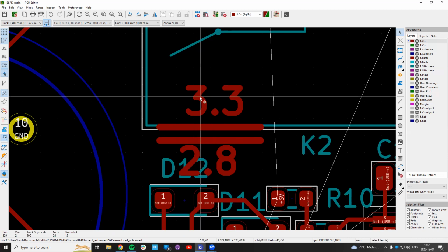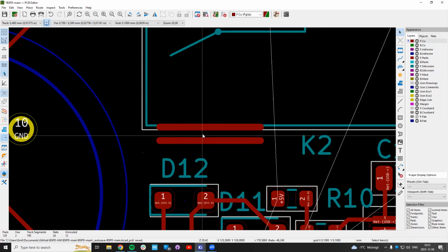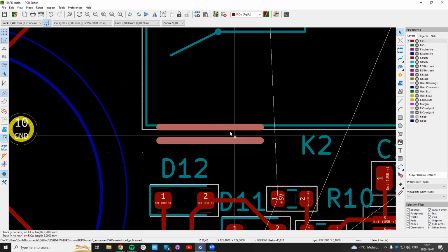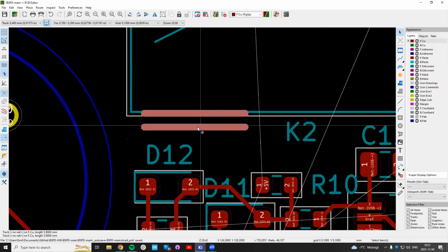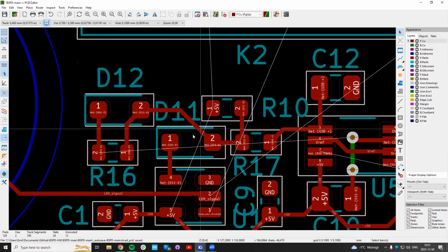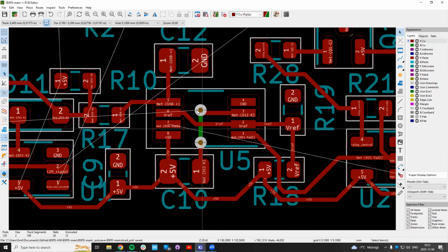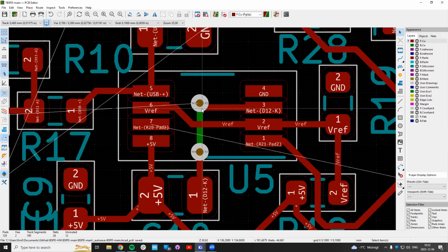This is a capacitor. So there'll be a stray capacitance coupling in between this. You call it a capacitive coupling. So it's okay, but just know that as soon as you start routing things close to each other, they will affect each other, even though it's very, very small things. It can actually play a role in the end, and it contributes to the quality of your measurements and your signal integrity on the boards.